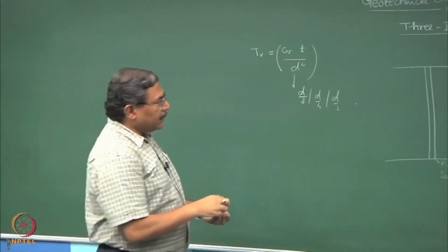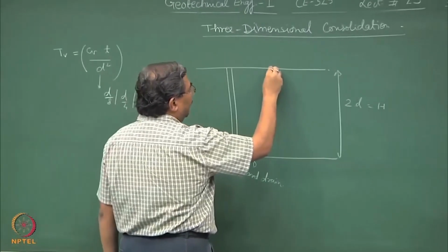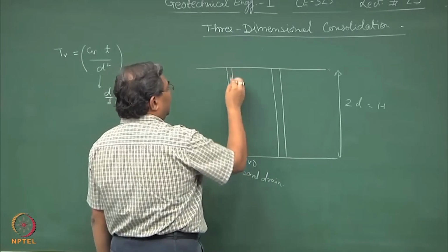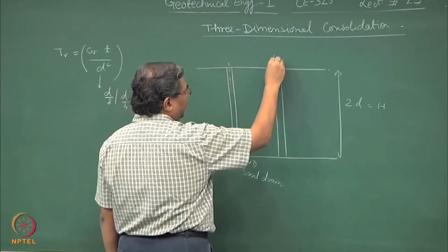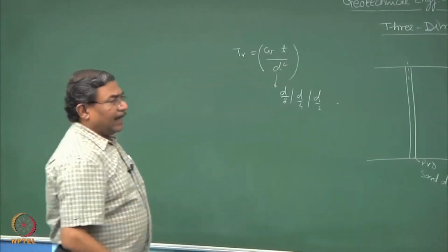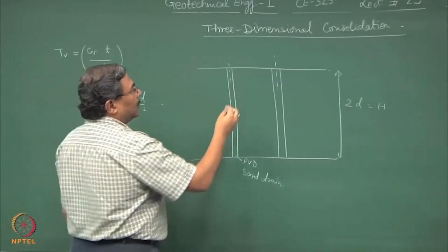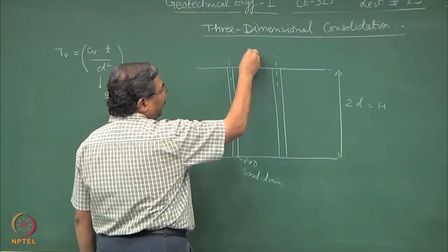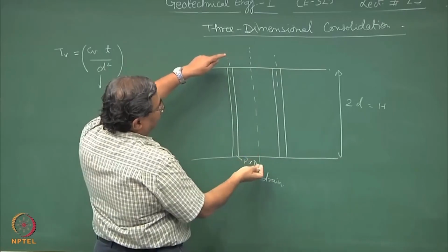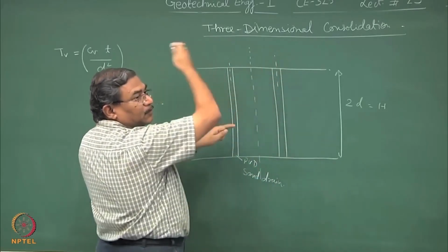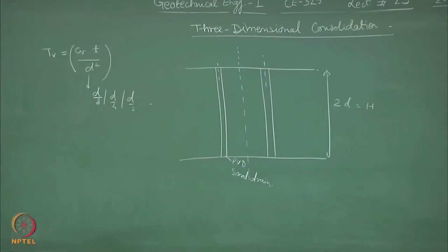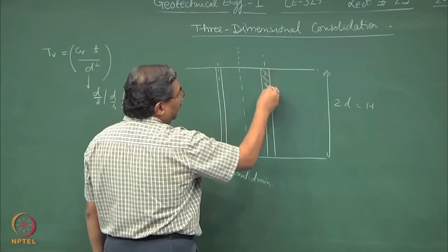Now, by inserting this, what I have achieved is, I hope you will realize that if this is the axis of these PVDs or the drains, I have reduced the drainage path. So, drainage path is now going to be somewhere in the middle of this system. If I rotate this whole thing by 90 degree, it becomes the situation which I have already discussed. So, these are the drainage layers, all right.